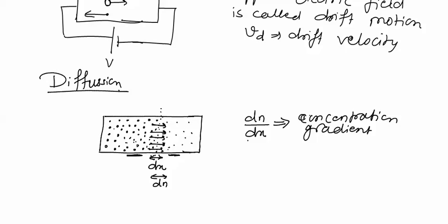As the charge carriers move forward, diffusion starts decreasing, and I can say that diffusion will die out where the concentration of electron in the material will be uniform. From this point diffusion starts, and at this point the diffusion ends. This is called L, diffusion length.